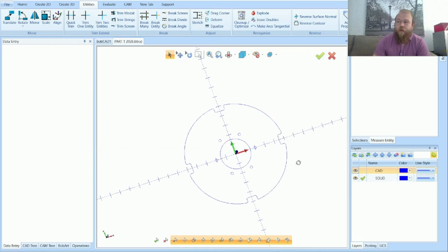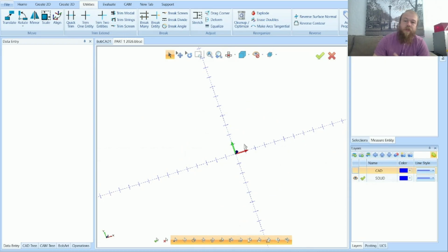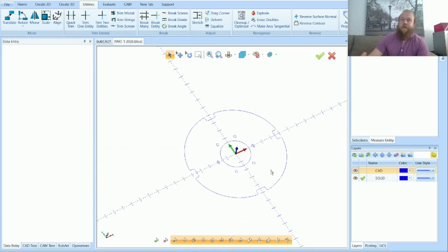This is useful when I'm making the solid model. I can select something and then hide the rest of the wireframe, so I'm not selecting anything else to extrude boss to make the solid, extrude cut to cut away from the solid. It's easier to hide everything from your wireframe to select exactly what you want to make as the solid there.